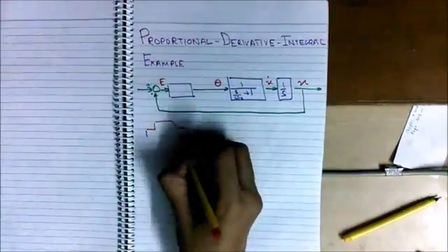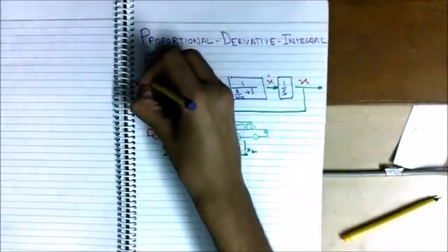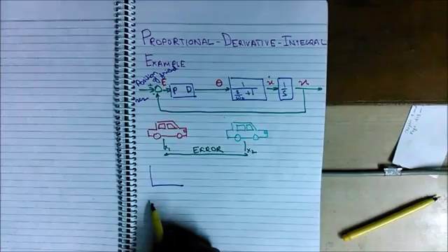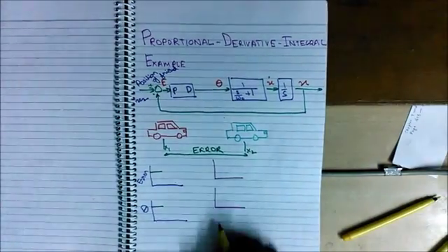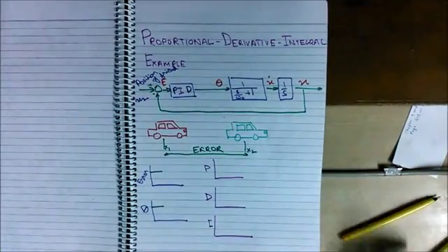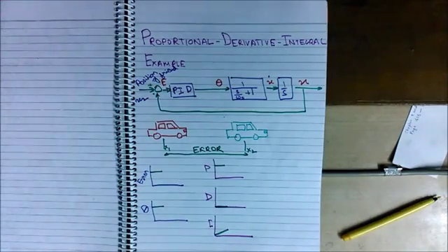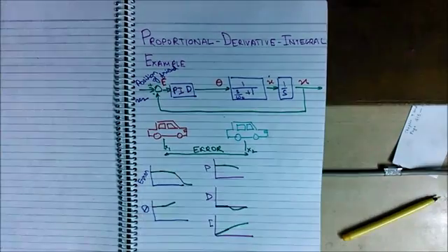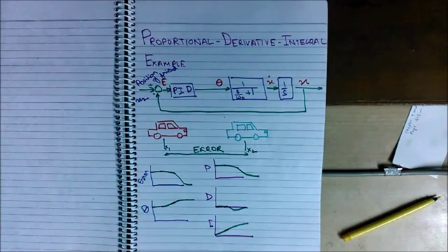Let's say you are at some distance behind your friend, but you both are going at the same speed, so there is an error associated. By increasing the gain, the distance between both cars is shortened. By controlling the pedal's position using a PD controller, the steady state error cannot be brought to 0. So, use an integral controller. The integral term sums up the error and increases the pedal's position, and so the car can be held constant at the exact position we need. Now, we can get a 0 steady state error too.